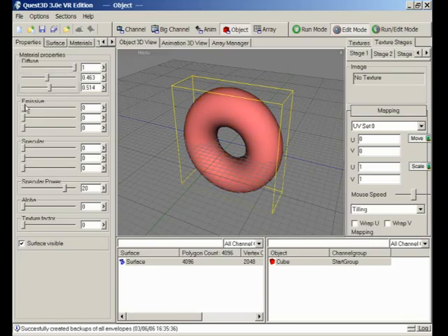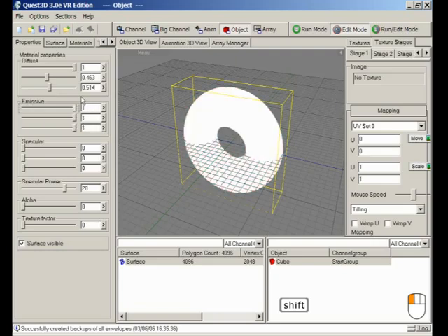The next one down here is the emissive. Now emissive is just self-illumination. So this is how the object will look irrespective of there being a light present or not. So if I turn this up to full, you can see our object is always white, no matter whether there is a light there or not.